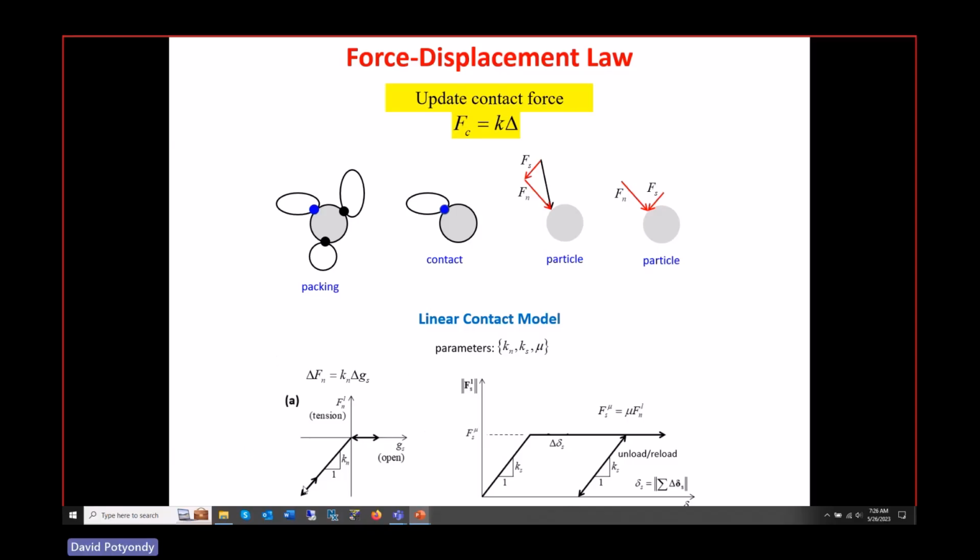Look at this picture. The ideal way to do this is I should be standing at a blackboard, but just pay attention here. This is not very hard. What we're going to do here is remember we have relative motion between those two surfaces. We're going to decompose that relative motion into a normal increment of motion and a shear increment of motion.